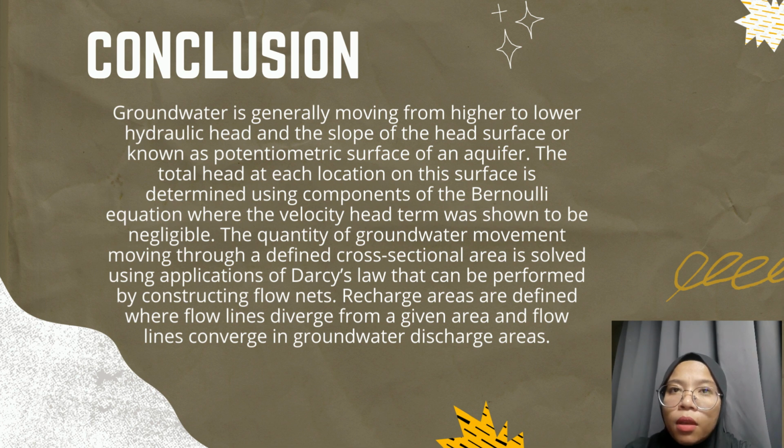There are a lot of reasons groundwater flow systems are poorly understood. The misinterpretation of level measurement was suggested as a key factor. Ignoring vertical flow, combining shallow and deeply completed wells, and combining short and long well screens contribute to the difficulty of interpreting level measurement data. Care must be taken to make sure the level measurement data are known to be from the same aquifer. Mixing level measurement data from different aquifers leads to misinterpretations of groundwater flow and may cause a host of problems.